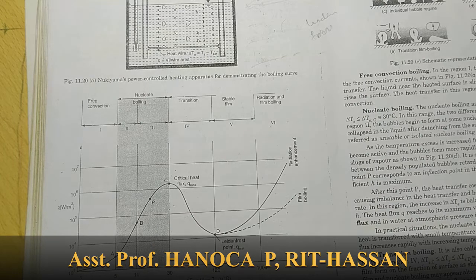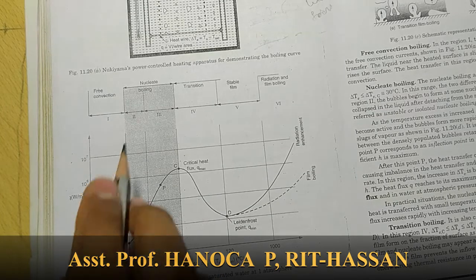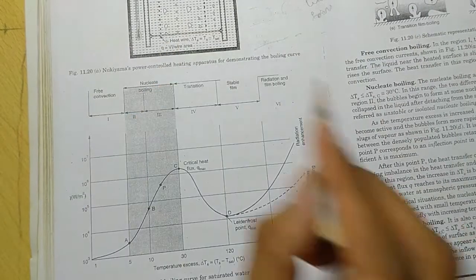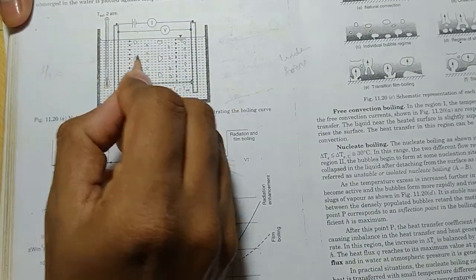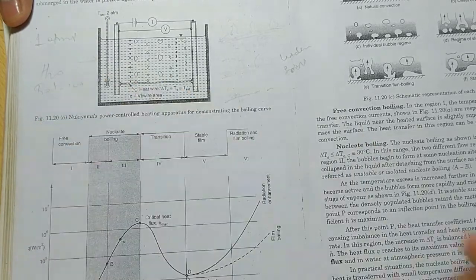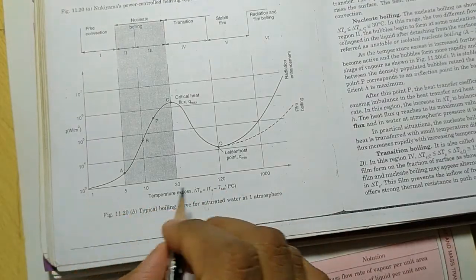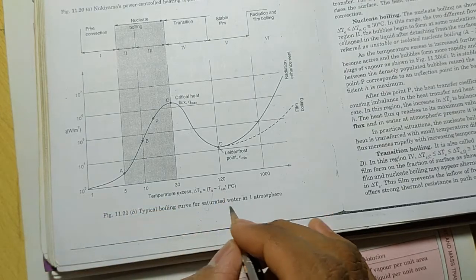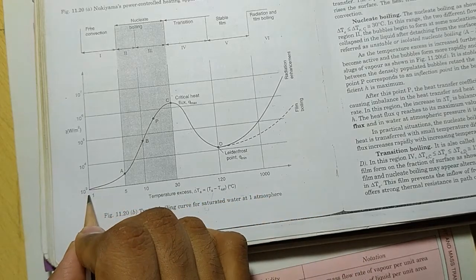Here you can see Ts minus Tsat. Ts is the surface temperature of this heater and Tsat is the saturation temperature of the liquid. Consider this is water at 1 atmosphere pressure. Then Tsat is how much? 100 degrees centigrade. Here 1 represents Ts minus Tsat equal to 1. Suppose Tsat is 100, and Ts minus Tsat is equal to 1, then the surface temperature becomes 101.